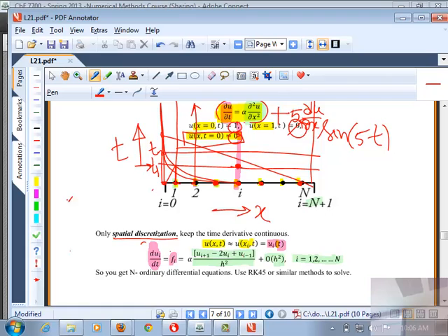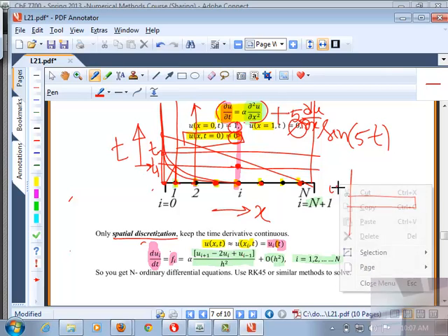If this is a heated fin, and this is x, the equation for that becomes du/dt equals alpha times d squared u/dx squared plus hP times (u minus u naught) or something like that. That is, the heat loss to the surrounding is captured by this term, the convection term, and that's a transient term. So the fin is initially cool, and then I heat it up. So there is a transient evolution.